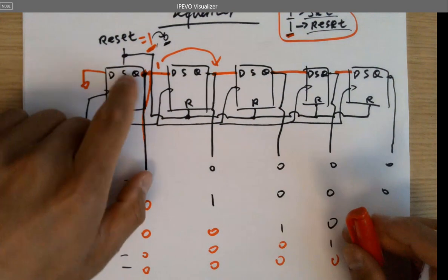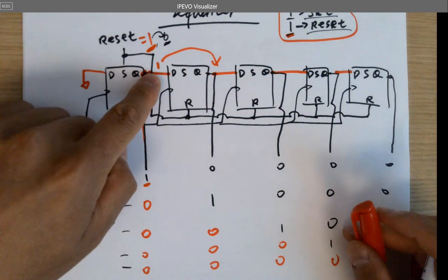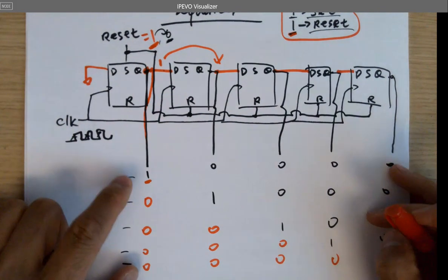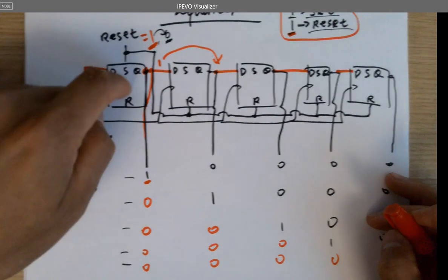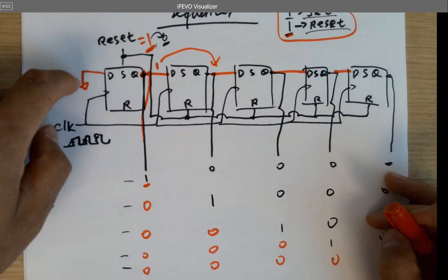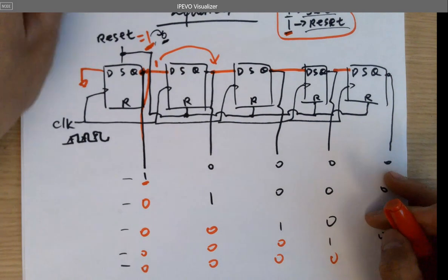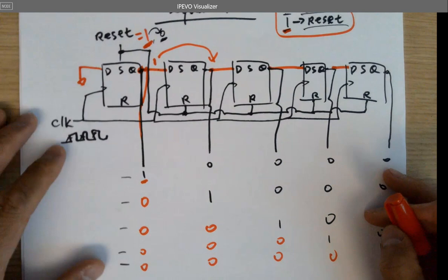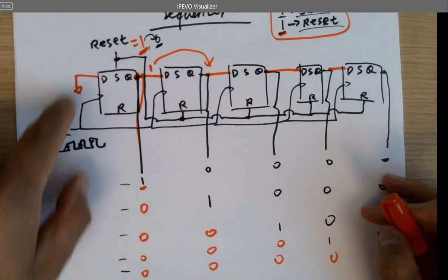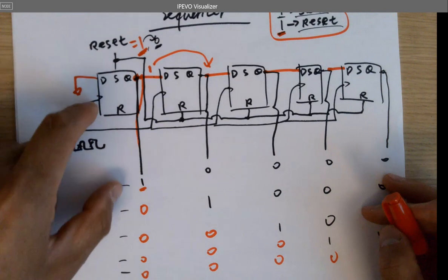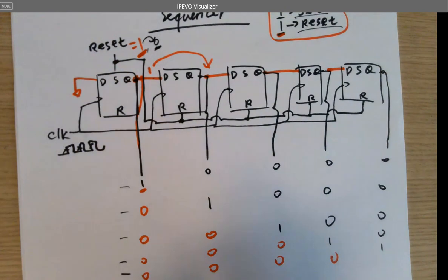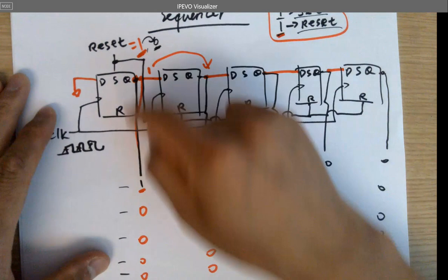So it's being forced to be 1. So you're definitely getting a 1, 0, 0, 0, 0 here at the very beginning, because this one is going to set it, no matter what you have at D. I talked about that at the very beginning of the class, right? Remember? You set it. So it's not a D flip-flop anymore, even though there's a clock rising edge. It doesn't matter, because this thing is being set. It's permanently a 1 whenever this is being set.